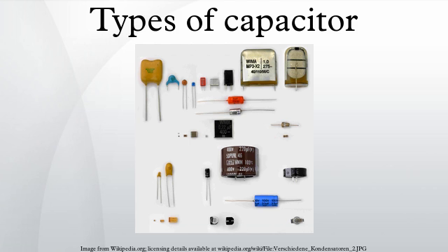In the series equivalent circuit, the electrical characteristics are defined by C, the capacitance of the capacitor; Rinsul, the insulation resistance of the dielectric, not to be confused with the insulation of the housing; RLeak, the resistance representing the leakage current of the capacitor; RESR, the equivalent series resistance which summarizes all ohmic losses of the capacitor, usually abbreviated as ESR; LESL, the equivalent series inductance which is the effective self-inductance of the capacitor, usually abbreviated as ESL.